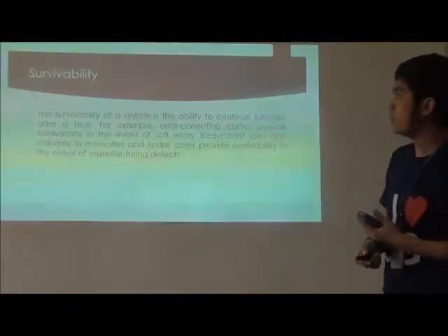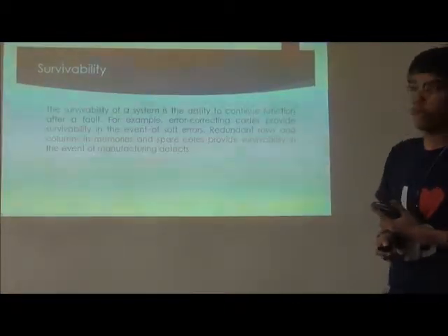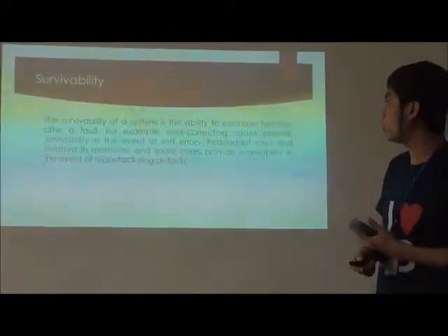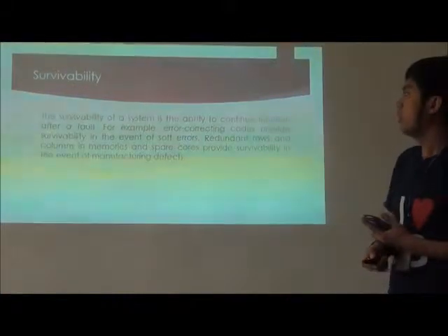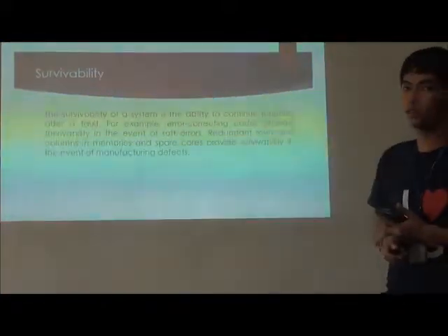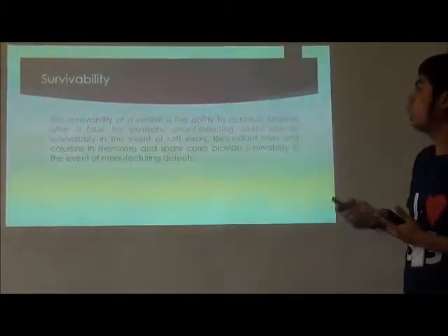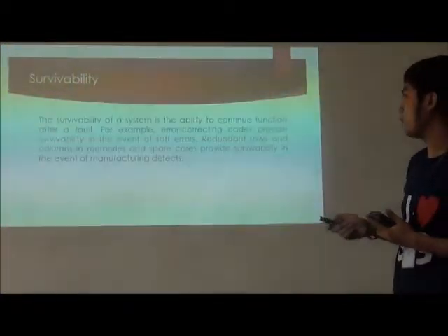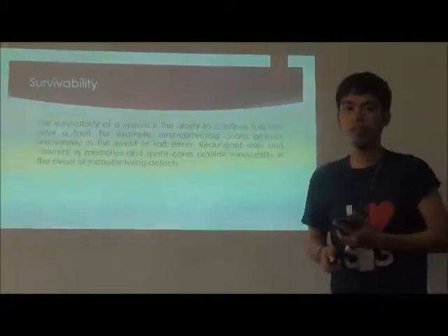Next one, survivability. The survivability of the system is the ability to continue to function after a fault. For example, error correcting codes provide survivability in the event of soft errors. Redundant rows, columns, and memory spare cores provide survivability in the event of manufacturing defects.